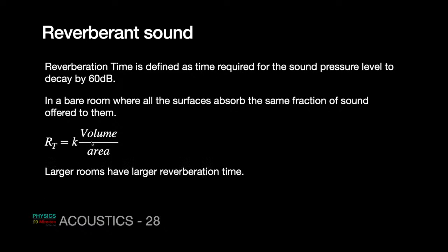Larger rooms, you can see that if the volume increases, length, breadth, height increases, volume increases, area will increase. But remember, area is the product of two numbers, volume is the product of three numbers. So volume increases much faster than the area, and therefore larger rooms have larger reverberation time. That is an important thing that we have learnt.